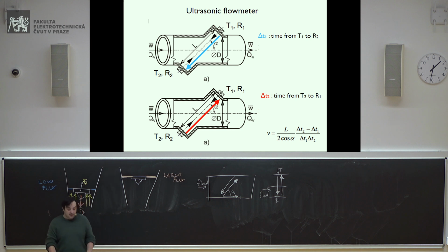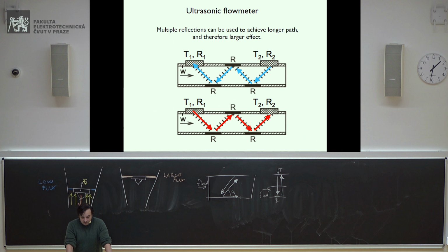So, let's say, again simplifying, one ultrasound is helped by the stream of fluid, the other is opposed, and therefore you will have a difference of time, which gives you the information about the velocity of the fluid.